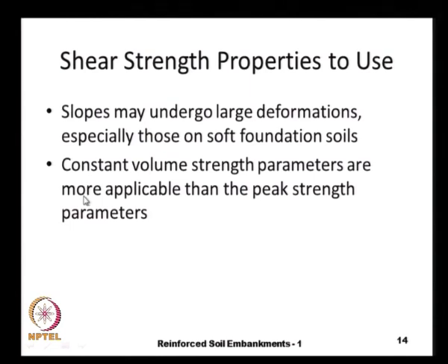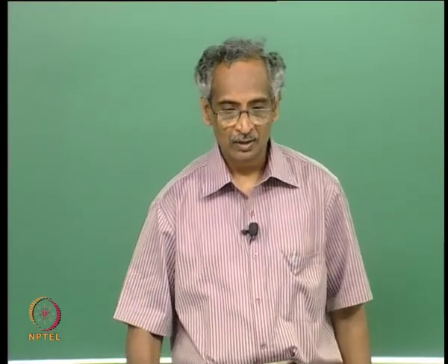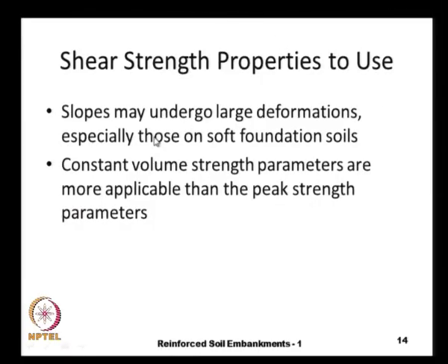What are the shear strength properties that we can use for design of slopes? We should realize even before we design that these slopes, especially those resting on soft soils, will undergo very large deformations, and because of that it is recommended in the design codes that we should use the shear strength properties corresponding to the constant volume state, or the constant volume strength parameters.